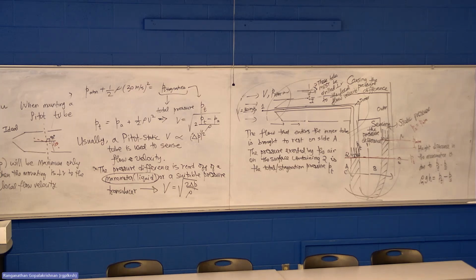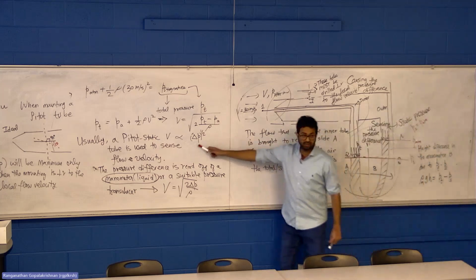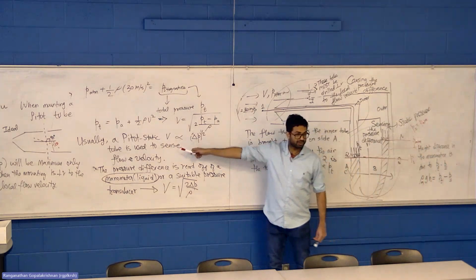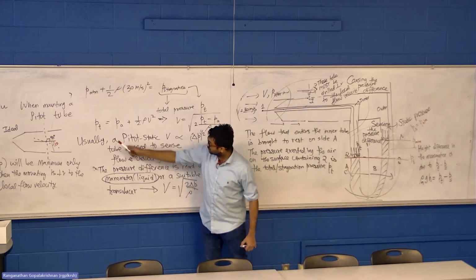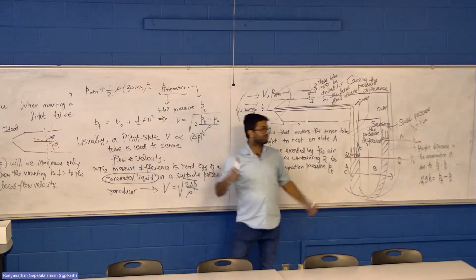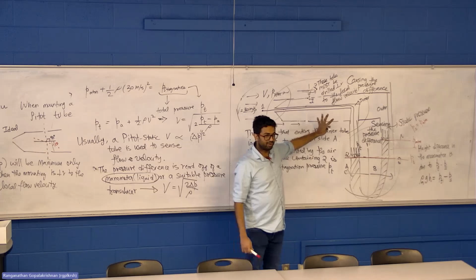Yes. So that rho g h is also just equal to the pressure through the motion. Yes, we are going to use this rho_m g h, the manometer fluid density times g times h, for delta P here in order to compute velocity. As I said, the typical usage is to use this as a velocity measurement device.